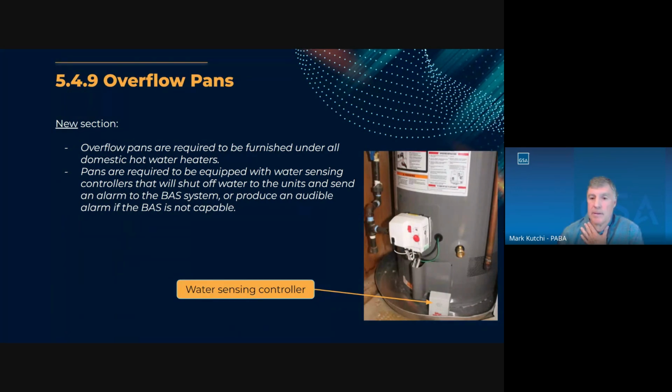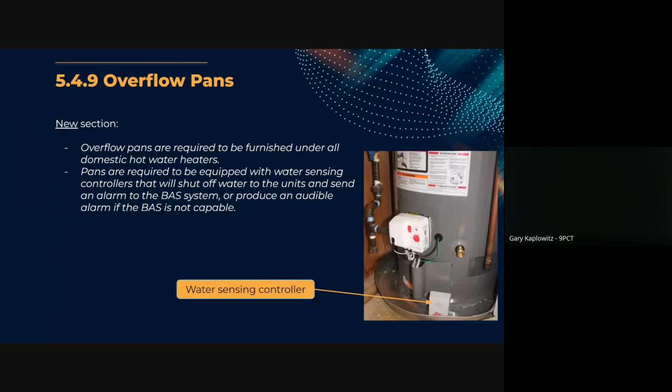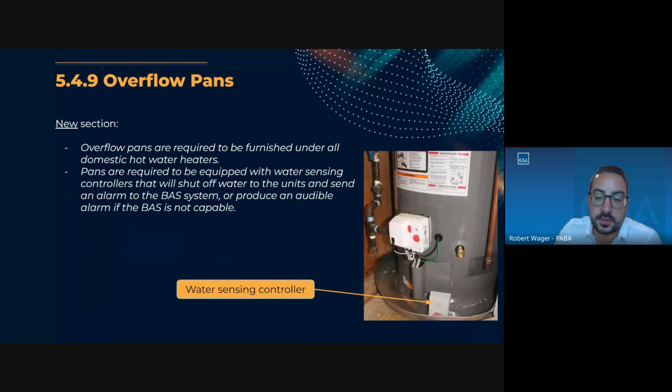Yeah, I was referring to a counterpart to a hose bib for the roof. If you have a hose bib terminating at the roof, it's considered penetrating the building envelope. Appropriate vacuum break and whatnot would be required, just as in any other conventional hose bib design.